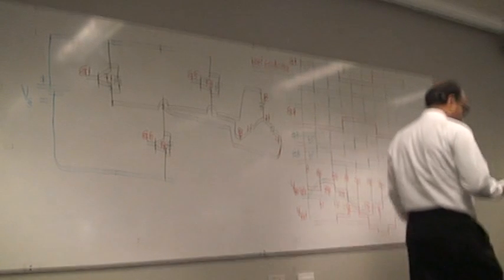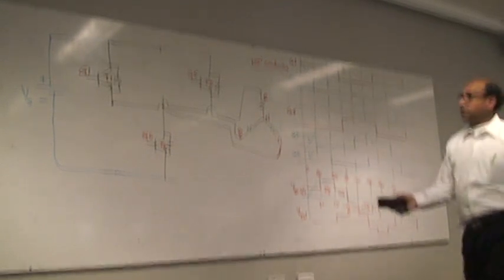One thing you need to get is how do I actually do the V by F control? I can control the frequency here. How do I control the voltage? One of the things most drives have is the input circuit.